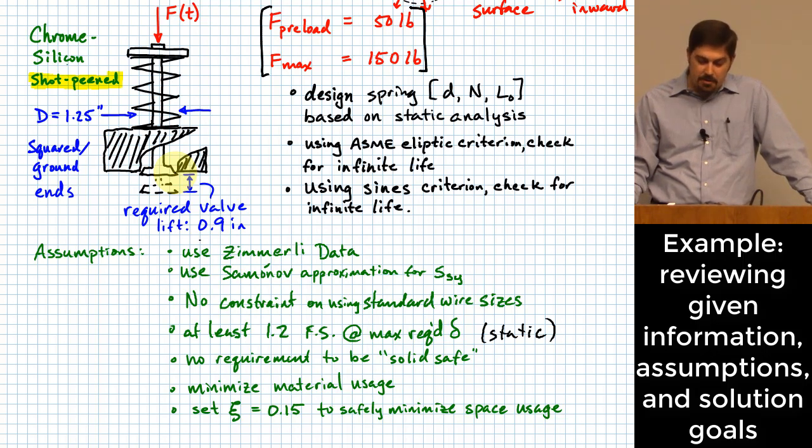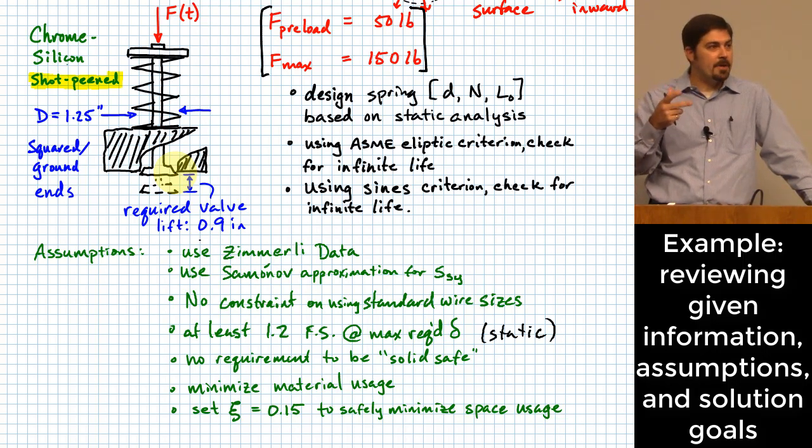And part of the issue here is the fact that the valve is not massless. So one of the things that can happen, especially in engines that have high RPM, is something called valve float, all right? Valve float is basically where the cams that operate the valves stop, and the mass of the whole valve train tends to keep the valve open instead of it following the profile of the cam, all right?